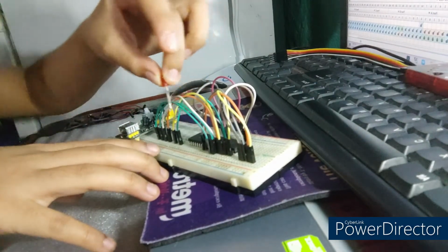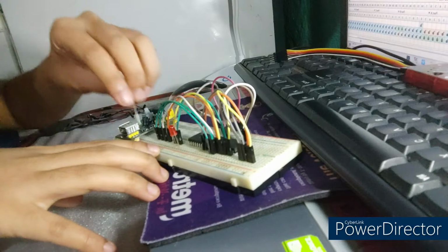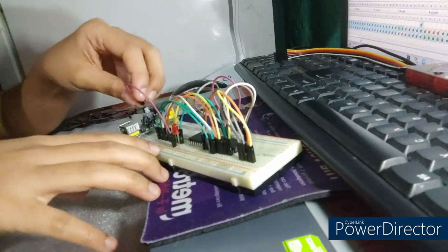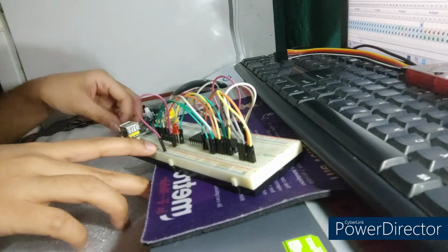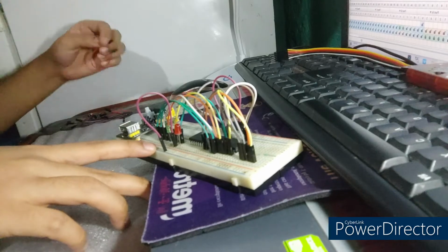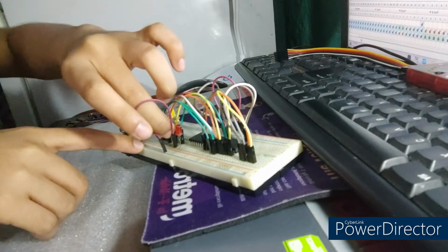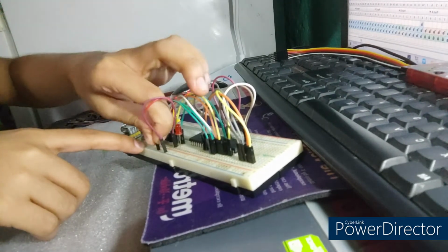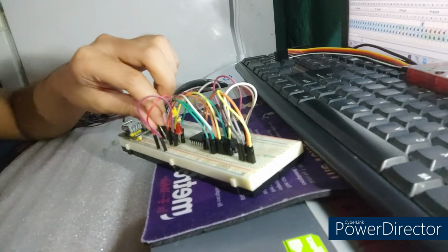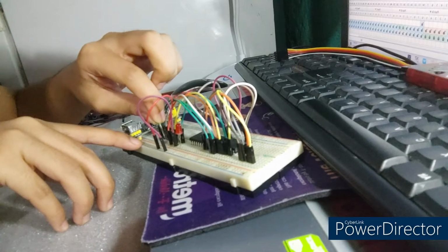So the first LED will be the red LED. So positive to negative, and then the green. So let's connect ground to our LED so it will light up. So let's put our ground here. Then next color will be green. So let's connect it here, and then let's ground it as well. And then we will also be connecting a resistor from pin number 4 to pin number 7 of our IC.